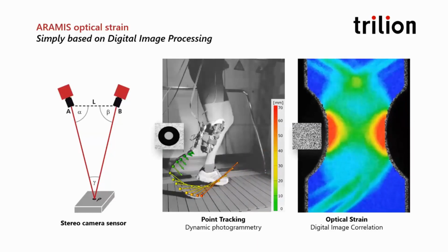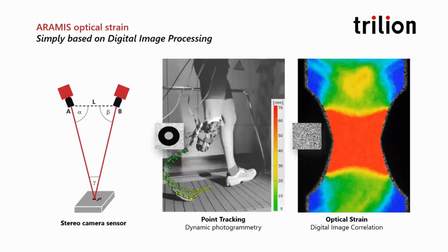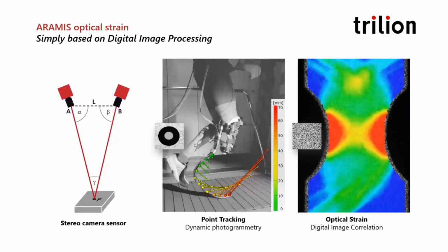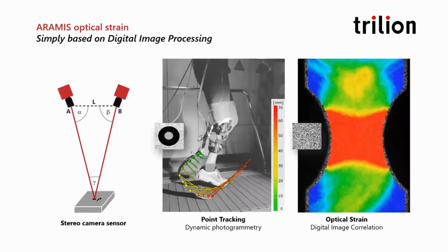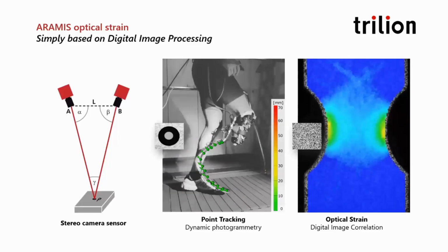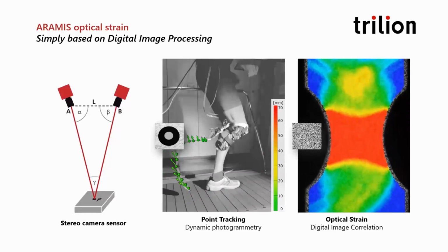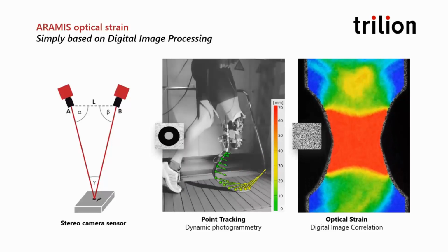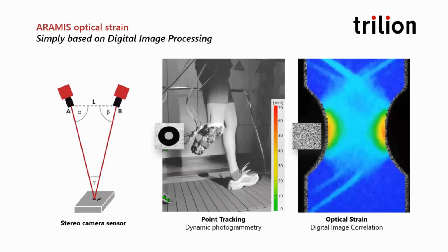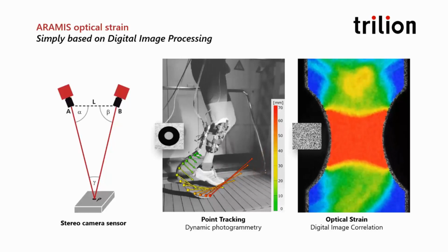This is a yielding effect that's really common in composite structures, but you can also see it in a lot of different metal specimens. You just don't see it with traditional clip gauges or strain gauges. So what you get from 3D DIC from the results are 3D shape of the component, you get 3D displacements, you get the 6 degrees of freedom, and the 3D directional strains. So you can see with all these results, this is very useful in biological specimens during in vitro or in vivo style testing that can get pretty complex.